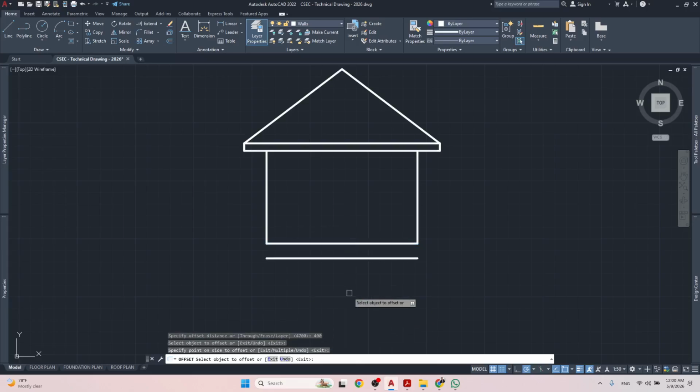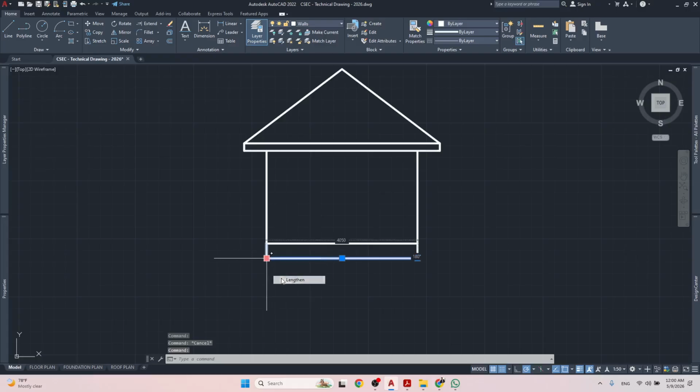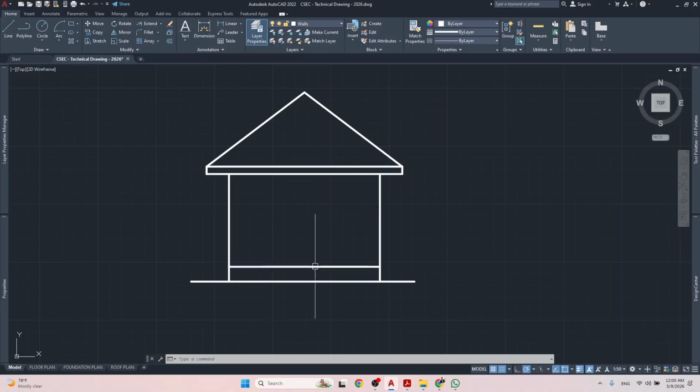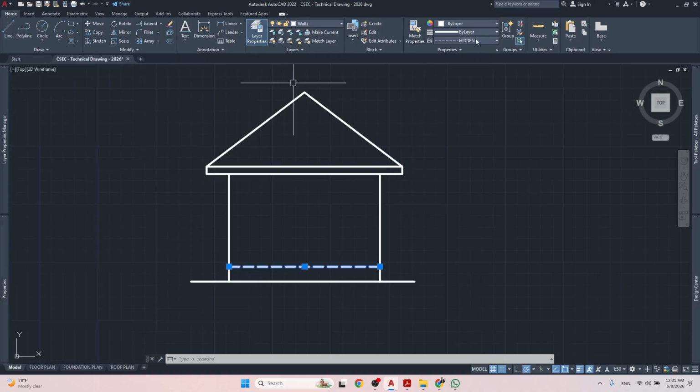So we'll do that. Now this is the floor of the inside of our house. This would be the ground on the outside. Right, so I'm just gonna extend some lines out like that to be our ground line. And let's think about it. If you are standing outside of this house, can you see the floor on the inside directly with your naked eyes? No, you don't have extra vision like Superman to see through this wall and see the floor. So that means this line should really be a hidden line. Okay, and then we'll make it a little thinner. All right, so there we have that.